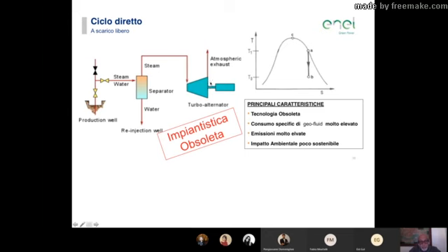Everything that comes out of the turbine goes straight to the atmosphere. So there is no condensation of the steam. Actually, you don't want the steam to condense, because otherwise the droplets of water will spoil the turbine. So you run only on the pressure that comes out of the well and is maintained and enters the turbine. Usually these turbines used to run at about 5 bars. 5 bars was the pressure entering the turbine, and then you had atmospheric pressure exhaust.